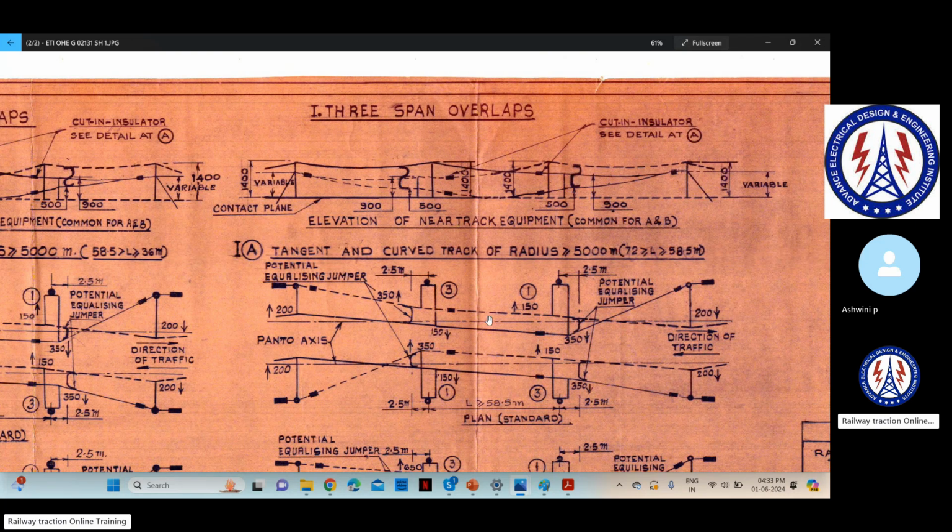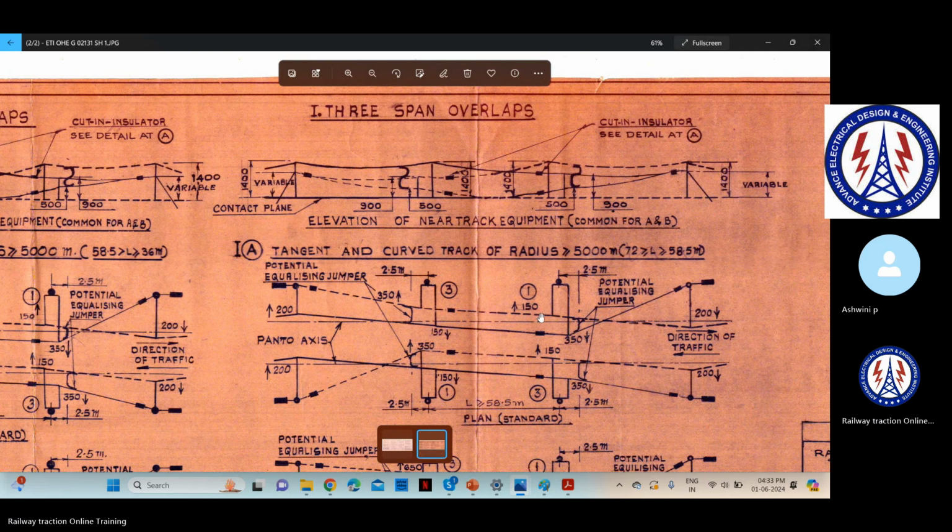So this will be good for seeing. I will provide an isolator over here. I will take a wire connection from here and supply it towards this point. If I open an isolator from here, this wire, my dotted wire after this insulator, will be dead. I have to provide another insulator over here because you can see this wire is crossing this dead wire.